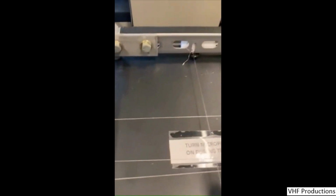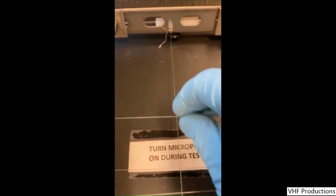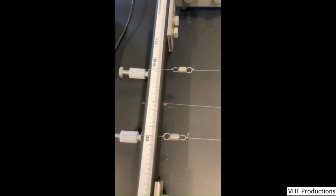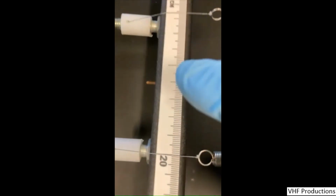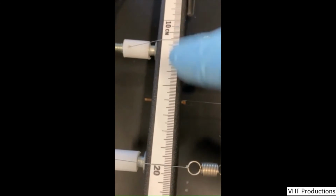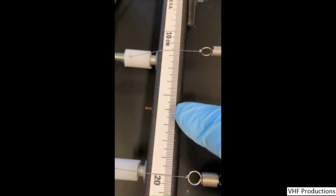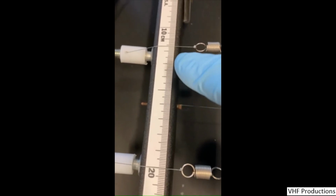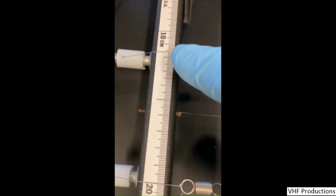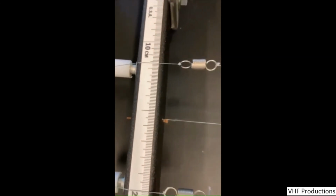Once the distances are set, the plank is centered over the 2 wires, and the microphone is moved into position centered above the center of the plank. Then the plank is struck by the hammer on the center of the width at the end of the plank in order to set up a longitudinal flexural mode vibration of the plank.